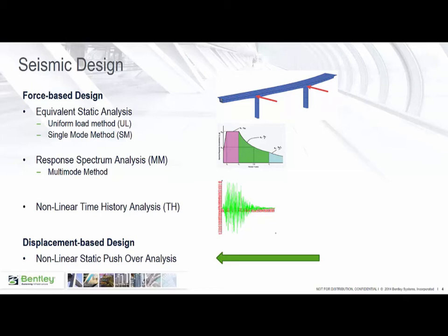Response spectrum analysis, or multimode, for bridges in which coupling of several modes in orthogonal direction can take place. Nonlinear time history analysis is used for important complex structures in poor ground condition and close to an active fault. The second common method, in fact this is becoming much more common now, is displacement-based design using nonlinear static pushover analysis.